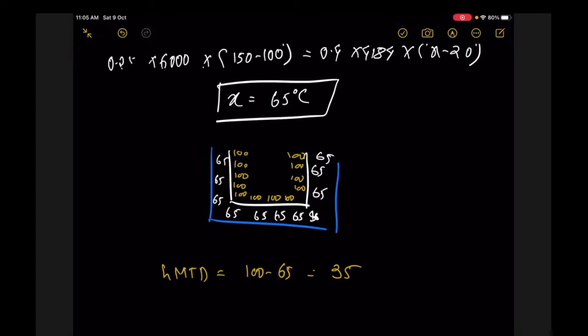Okay, just like evaporator and all that. Here, there will be the exchange of heat, but not according to the pattern which we have studied, that of shell and tube. Basically, in shell and tube, one thing is going in one direction, another thing is going in another direction, and it helps to get whether it is co-current or counter current. But here it is not a direct heat exchanger. Therefore you can say it is a special type of heat exchanger, and that too they have installed a stirrer, which makes things different.